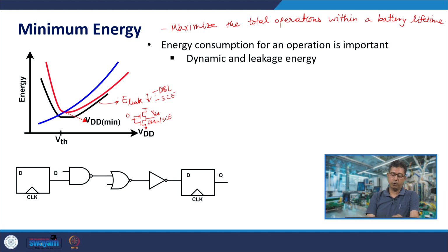But there is also another effect which comes into being. As we go ahead, we will see that the leakage energy is not only dependent on leakage power, but it is also dependent on the time period. As we will discuss, the time period would increase as you reduce the supply voltage. We will discuss this further, and therefore, the leakage energy increases beyond a point, and that is what we are observing here, that beyond this point the leakage energy is increasing per operation.